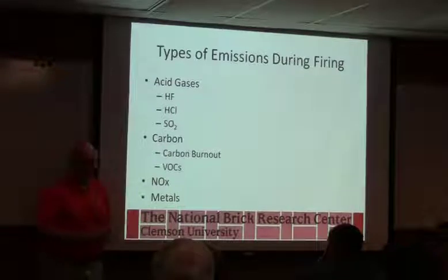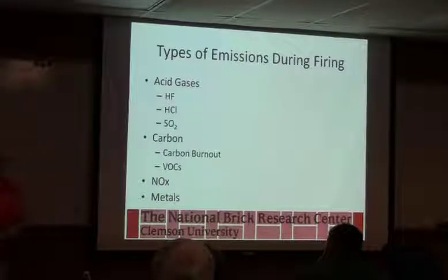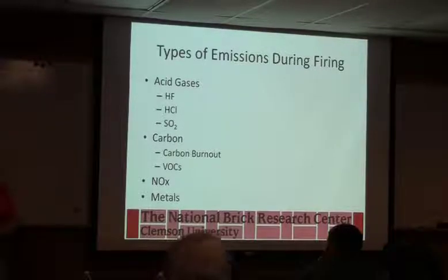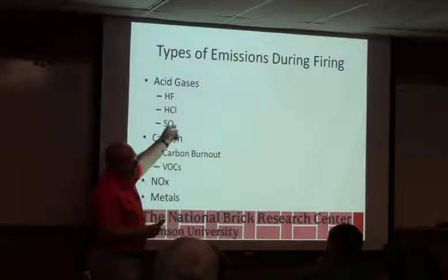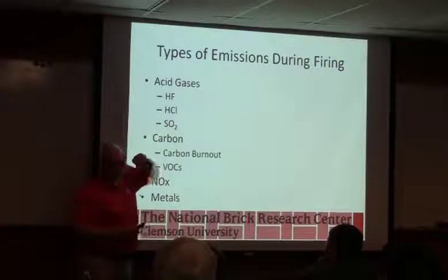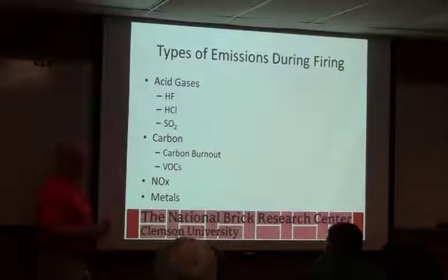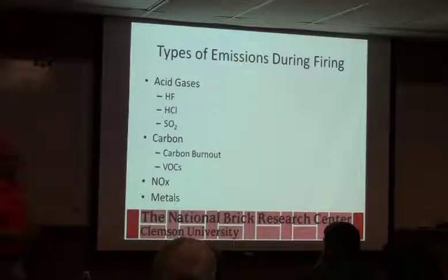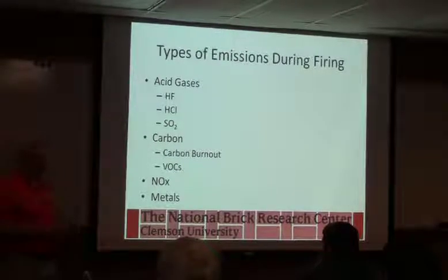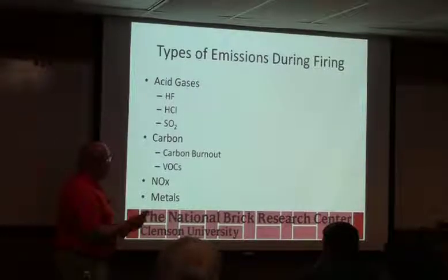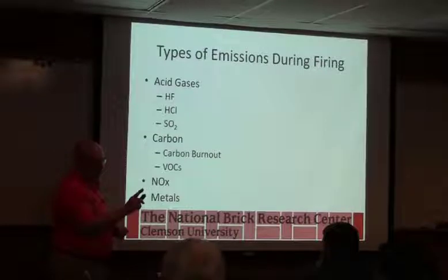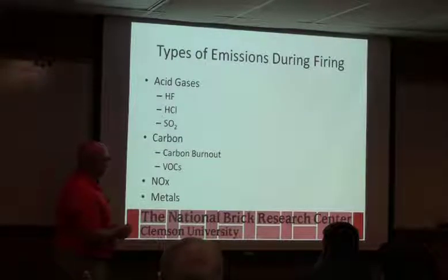Do any of you get any black or green gunk that builds up in your exhaust ductwork? That's actually a form of sulfur. It's an ammonium sulfate. It can be an ammonium chloride that forms in your exhaust. It's called a condensable particulate, and it collects in those spots, and it's nasty. But that's not regulated, and we'll talk about why in a minute.